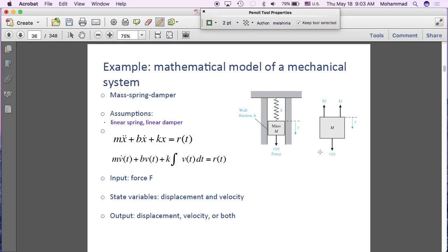So we're going back to motion and mechanical systems. What I'm showing you is a system that has an inertia, mass m. It has an energy storage element, which is the spring, and an energy loss element, which is the friction. And what we want is to capture how this inertial element, how this mass moves. So we want to capture its displacement, which in modeling language means I need a model. I need a differential equation that describes the motion of this system.